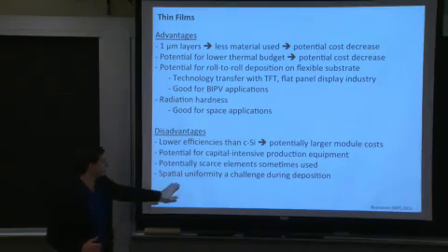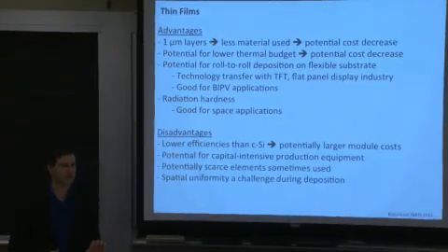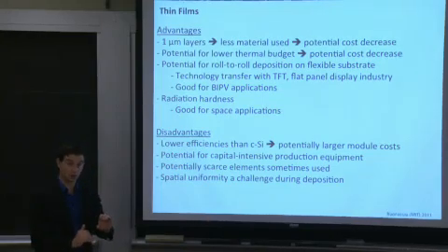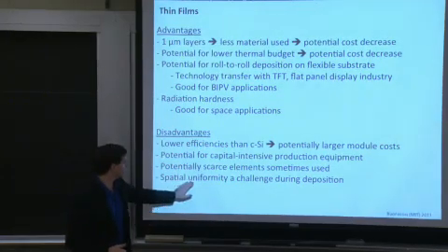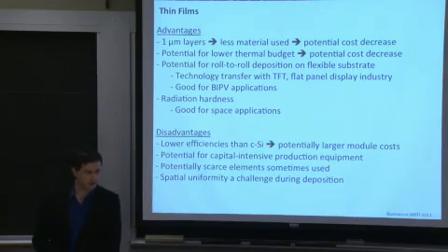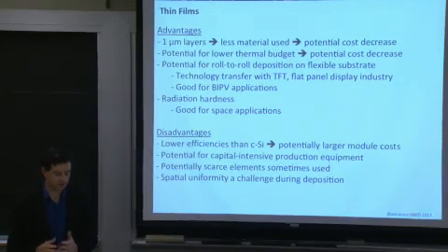So we have to somehow deposit a film a micron thick, and layers that are even thinner, that might be only a few tens or hundreds of nanometers, on top of and below that absorber layer to separate charge, for instance. And that's really challenging to do on a very large scale. And that is an engineering challenge, or a process engineering challenge, that had many startup companies flailing for a long time.